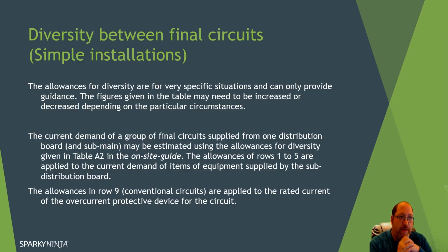Your key point in question would be your project, which is a test centre for 2017-18. That's a type of system or a type of building that is not similar to any of these, so your diversity will be different to these requirements, because you'll be thinking, well, a lot of these circuits are actually not going to be used for demand, they're going to be used for access to a source of supply.